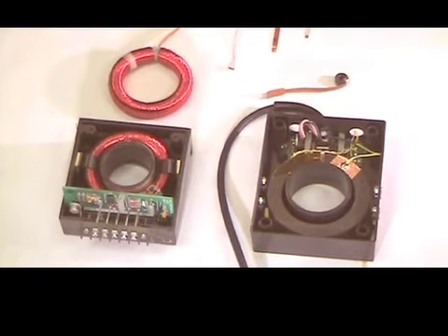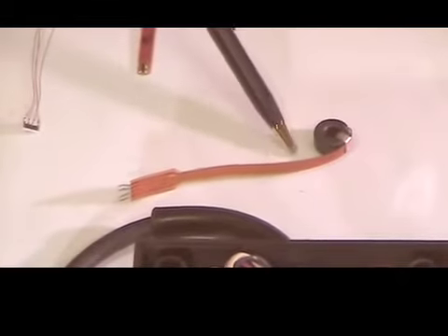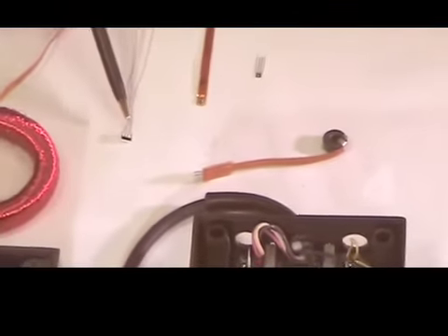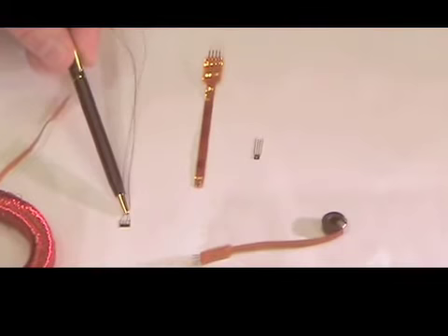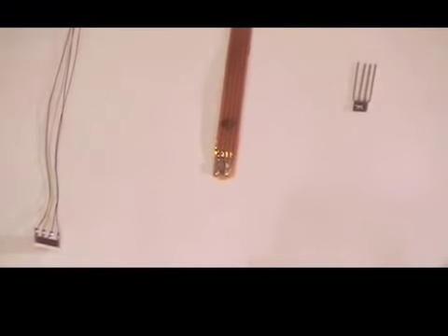Up above is just an example of one of the most simple forms of the open loop sensor, where you have the Hall sensor on the end of this flex strip and a gap in the core, and that's the complete sensor right there. We've also brought examples of Hall probes. This is an OSI Hall probe right here, much like the drawing that we showed earlier when we were explaining the Hall effect. These are a couple of commercial Hall probes. This is a surface mount Hall probe. This is a through-hole Hall probe.